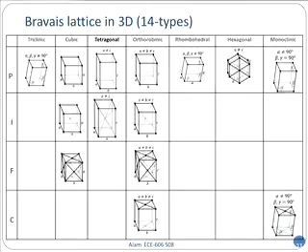So you can see, starting from the top, the triclinic has this alpha, beta, and gamma. These are the 3 angles among pairs of lattice vectors. None of them are equal to 90 degrees. So that's the most general form. Then you can have cubic, all 3 sides the same, angles 90 degrees, no problem. Tetragonal, and you can see the 2 sides are the same, the base is the same, the height isn't, the height is a little longer, and then onward you have more.